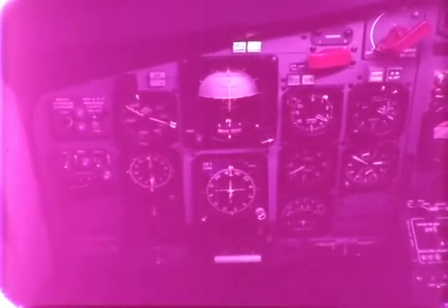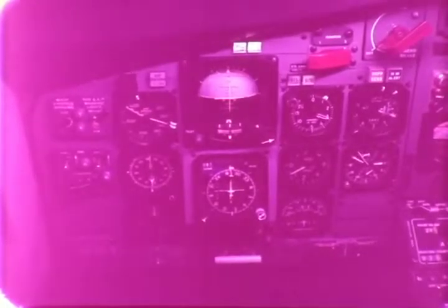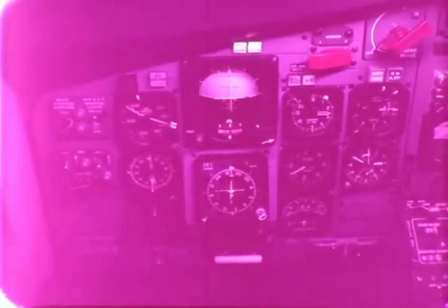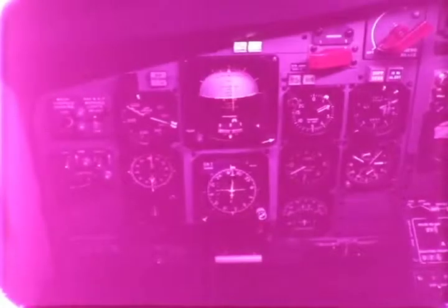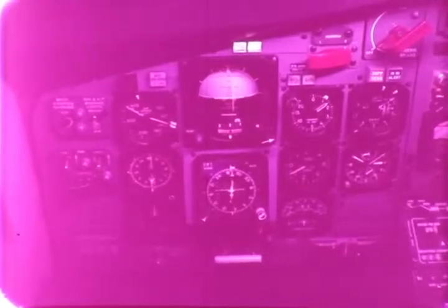A missed approach caused by excessive track changes. 1,200 feet visual range, night. Approaching 200 feet above minimums. Looking for lights, none. Coming up on the middle marker. Expanded localizer shows us drifting to the left. Expanded localizer at maximum allowable deflection. You look for lights, there they are to our right.